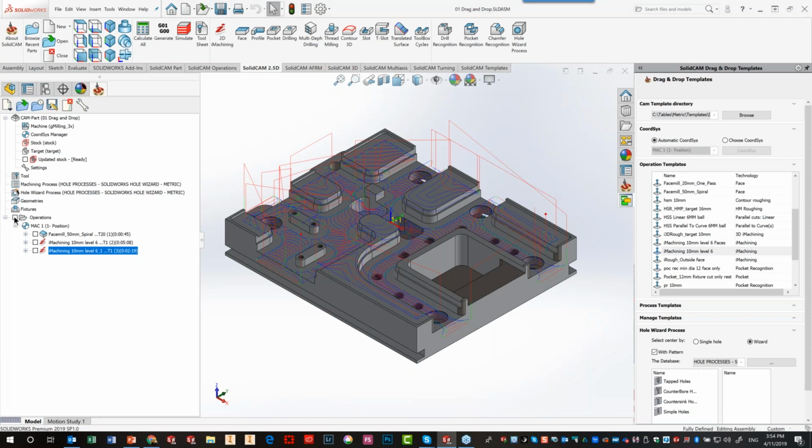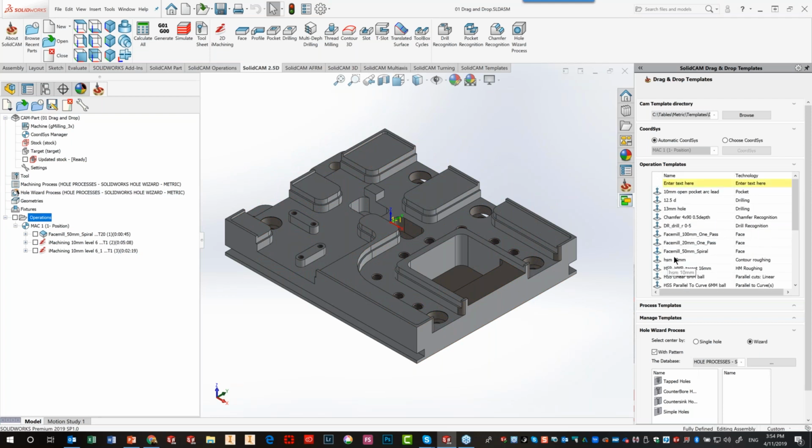I want to put another one over here on the side, but I don't have a coordinate system for that. Well, what happens is very simple. I'll take a tool path over here, face mill operation, put it on this side over here, and what's happening here, it creates a new home position automatically and puts the tool path on that side as well.